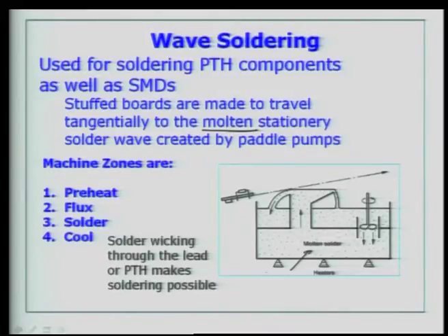There are heaters that keep the solder molten at all times, and then using some kind of a paddle pump you generate a kind of a wave. As you can see here, a wave is generated at the top. Now, your PCB with the component inserted, especially the through hole components here, is made to move on a belt tangentially to the wave. So, the wave touches the leads of the through hole components at the back side or the solder side of the board,